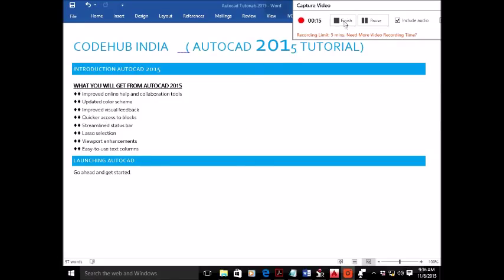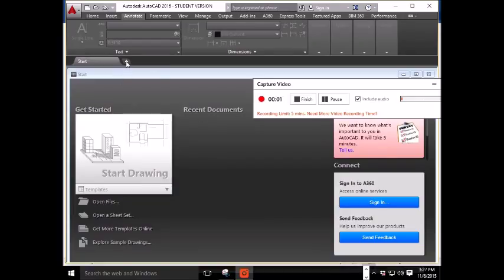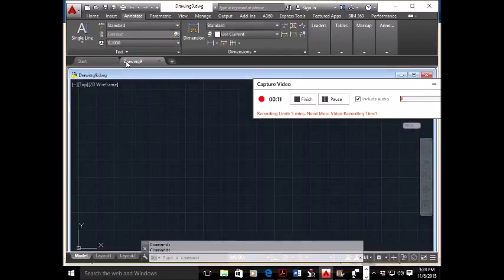As mentioned, at the bottom of the screen, just above the status bar, is a small horizontal window called the command window. Here, AutoCAD displays responses to your input while you're using a command. By default, it shows one line of text. This line shows the current responses to your command input as well as command options. As you work through a command, you'll see more responses, with earlier responses scrolling upward in faded text.